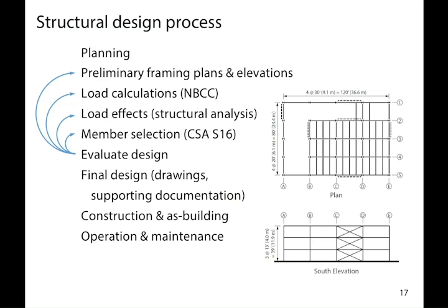Preliminary framing and plans and elevations. Basically somebody needs to say, okay, what are we going to build? How do we think we're going to build it? And that generally comes down to input from the architect and the structural engineer. Sometimes the mechanical systems, or if it's an industrial system, oftentimes buildings are built around the process. And so if you've got heavy industrial facilities like you've got in St. John, for example, you build a building around the equipment and the process machinery that's making the things that they're trying to make. And so sometimes it's in collaboration with the process engineer.